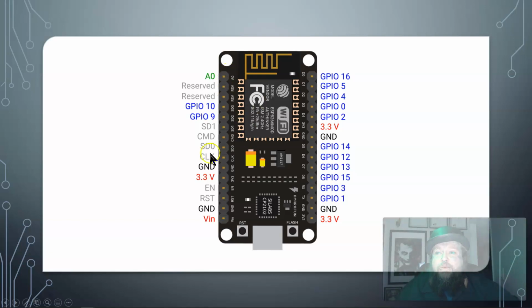But the idea is that it will have prongs, basically conductive points that you can connect other conductive material to, and each one is then labeled, and you again have the GPIO. So this is just trying to hammer home the point that once I know the controller I'm working with and I've picked it, you need to worry about what it provides for these pins, which again, the number of them and how many give you limitations depending on what else you're connecting, but you need to look up this specification and always keep this in mind when you're working with it.